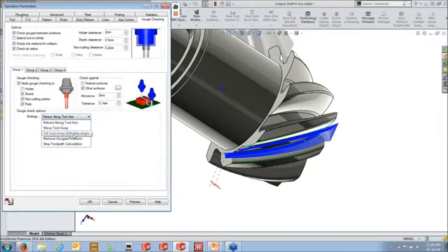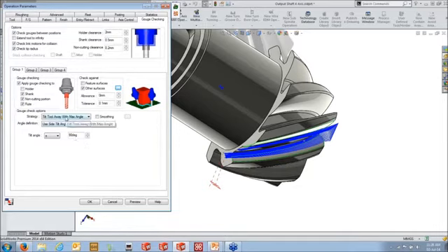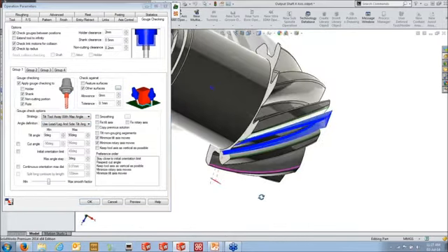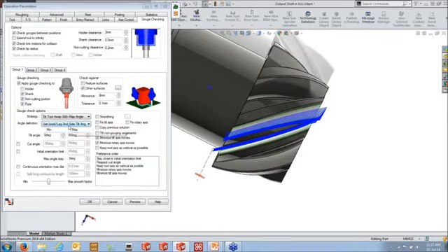And then I want to tilt it away as well. So I want to use some tilt control rather than moving the tool away in like an XY linear move. I want to make sure the actual tool tilts away with a rotary move. So I'm just going to use some of the lead, lag, and side tilt angles now. Because we're actually using the fourth axis, these lead, lag, and side tilt angles aren't relative to the actual rotary, it's relative to the surface. So my side tilt is going to be in this direction here.